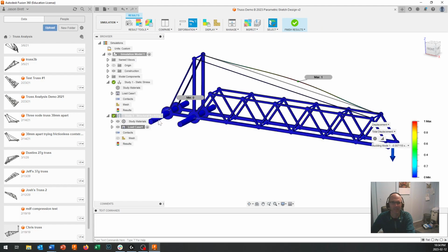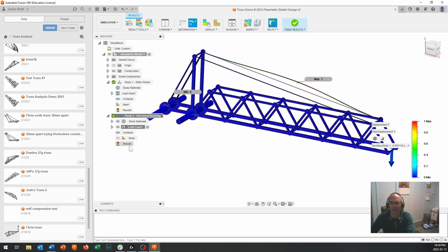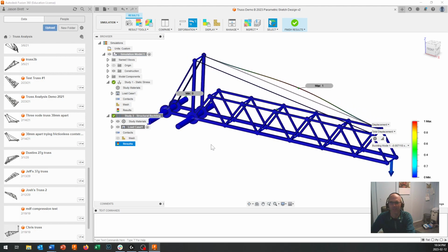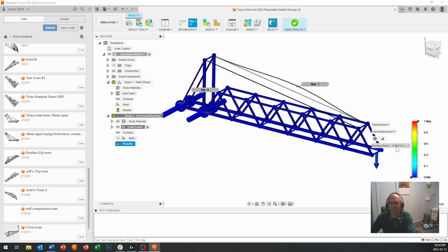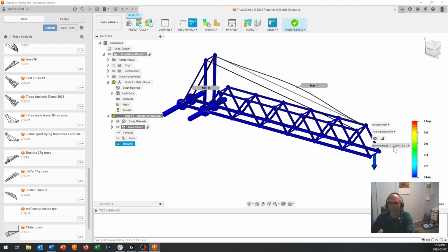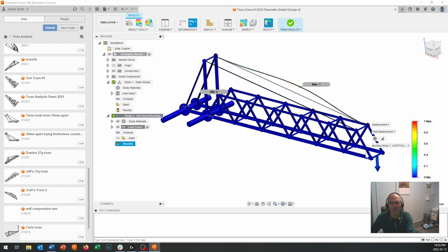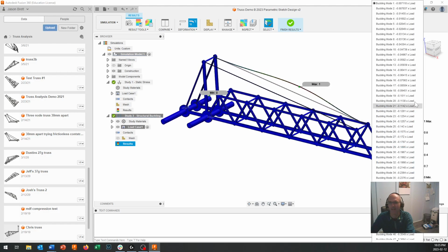Okay, but let's see, the structural buckling just came in, and maybe that's going to put a damper on my enthusiasm, because here is my structural buckling study. If I come in here to my results, okay, well, now buckling mode 1, keep in mind it's negative results. So if we're pushing up on it, everything's nice and stiff. We've got to come down here until we find the first